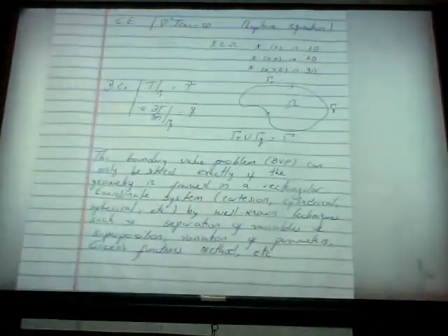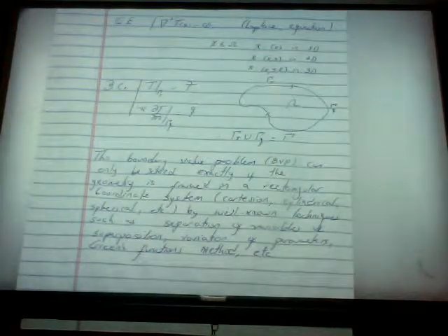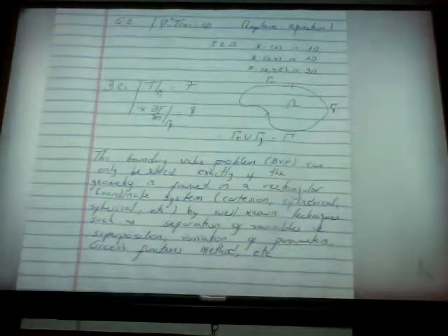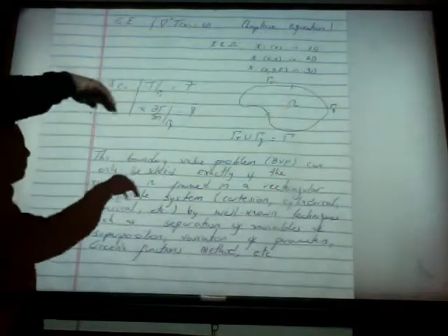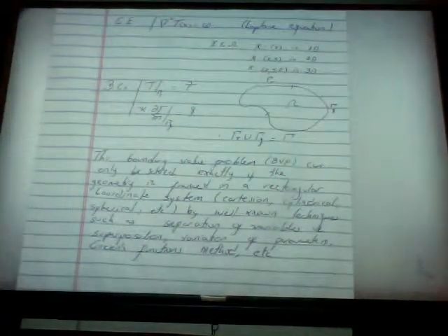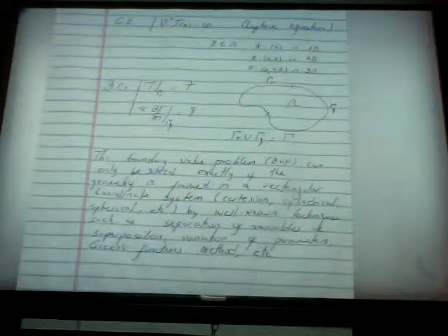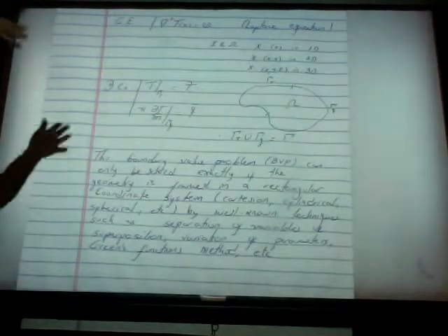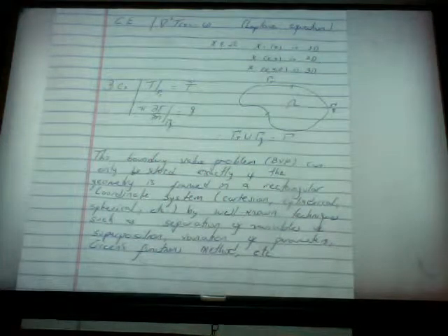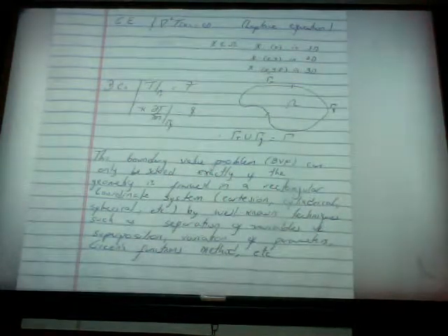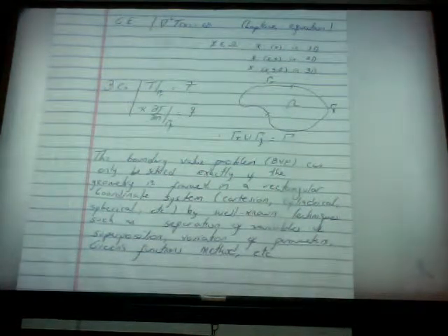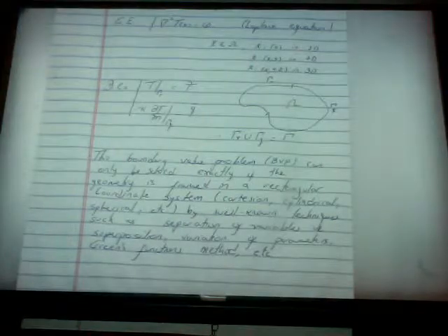So, what do we do? If we want a solution to this problem, we resort to a numerical approximation. If we want to do finite differencing, we know that we have to have a sequence of points, a regular distribution of points in a counter manner. If we want to do finite elements, we know we have to mesh that domain into elements and use polynomial shape functions within each of the elements. But we're going to do something slightly different now.